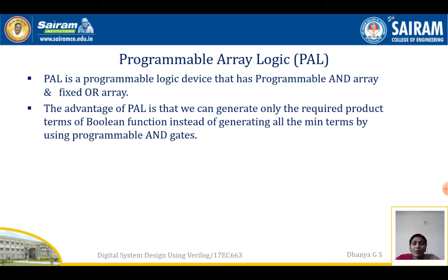It is a programmable logic device that has a programmable AND gate and a fixed OR gate. The advantage of PAL is that we can generate only the required product terms of a Boolean function instead of gathering all the min terms by using the programmable AND gate.